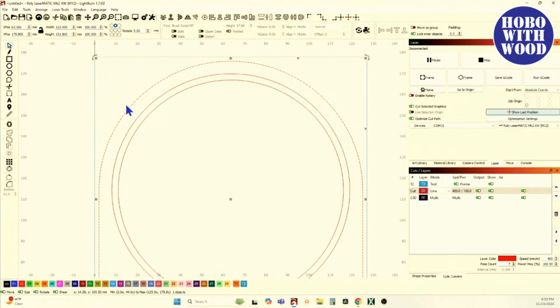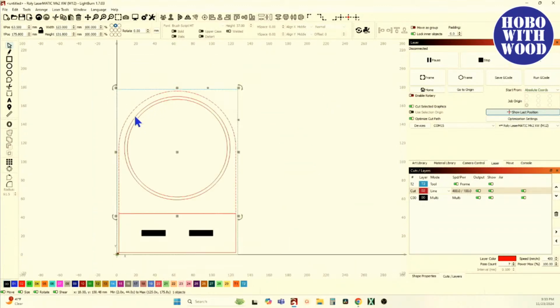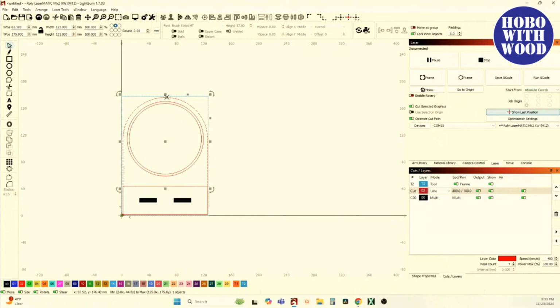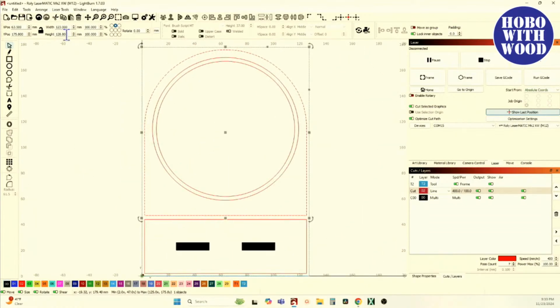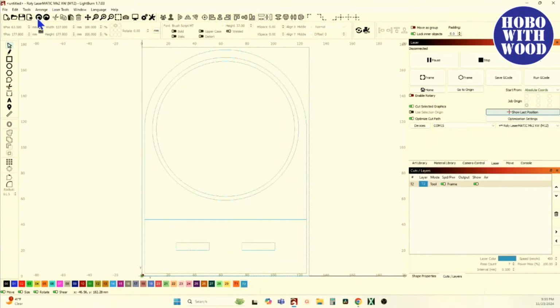If you look, this radius matches that radius. It's a good mirror image. But if I've got my anchor point at the top of this and I tell it I want to change the height by less 3 millimeters, did you notice that radius changed? In fact, I'll exaggerate it. Let's undo and let's do that less 10 millimeters, so you can really see that. You see how that jumped up and changes that? Now, a fast runner may never see it, but I see it. It's glaring.